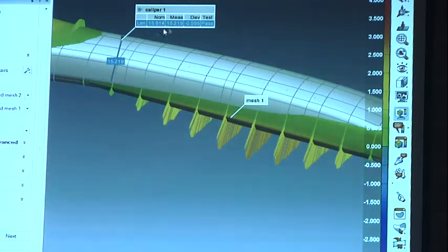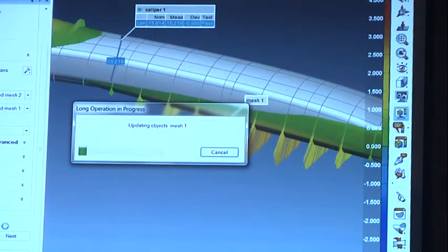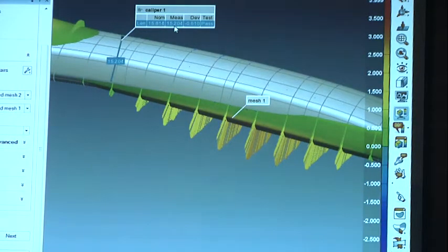So if I click Apply, not sure how much it will change, but this value will change accordingly. So it's 15.219. If I update my best fit between my 2 meshes, it will update the unified mesh, update the best fit with the CAD model, remeasure or update the caliper as well. So it's now 15.204. So it did not change that much because in this case it's just using all the points instead of a subsample. But let's say you would have changed the way you align them using remeasuring a plane or something, or adding more targets if you use probe targets, it would update everything.